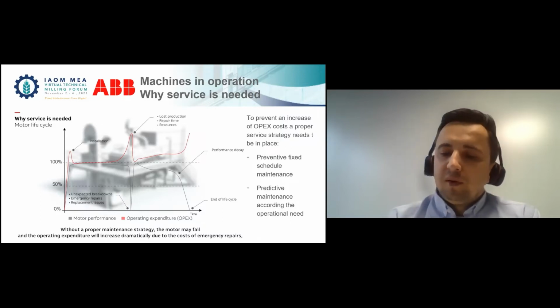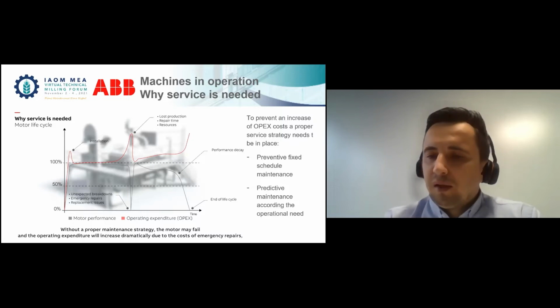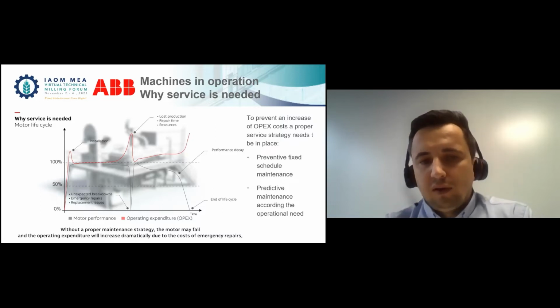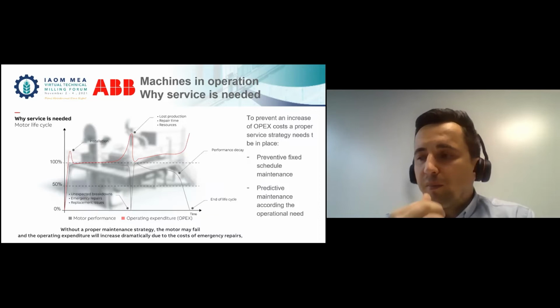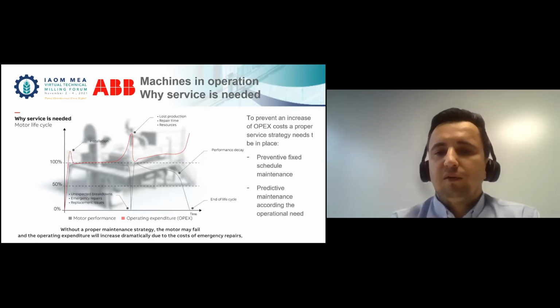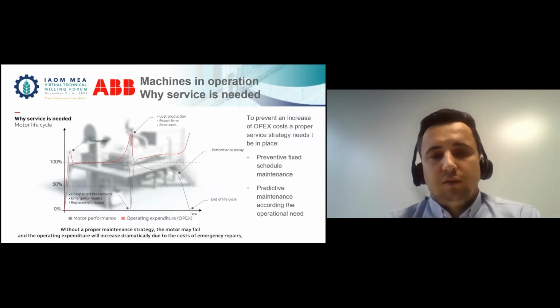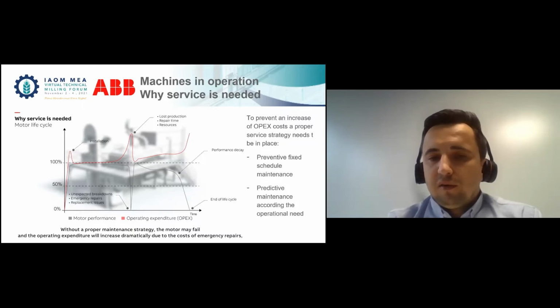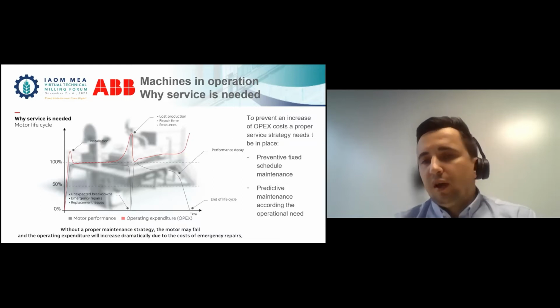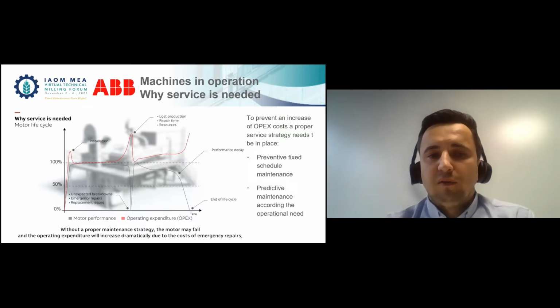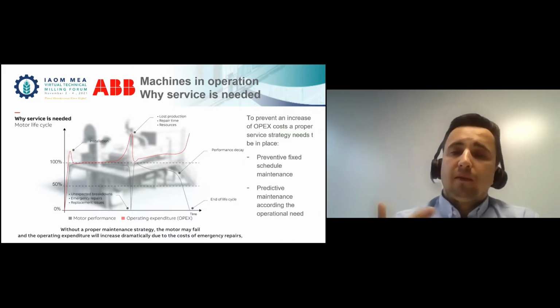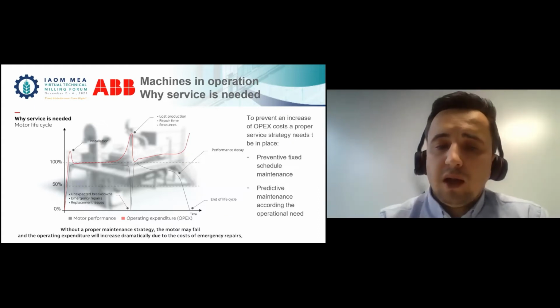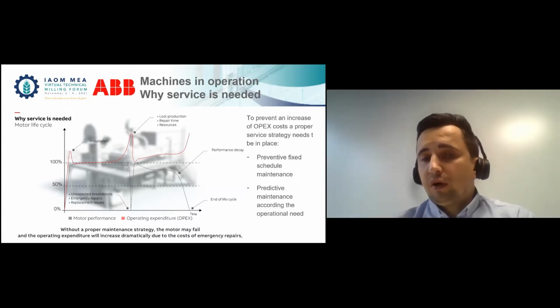But the motors do not come by standard with a specific grease, and this is also part of the application requirements, and very important. So if you have huge bearing forces, radial bearing loads and such, high temperature, high speed, you have to adapt your lubrication intervals to avoid unexpected breakdowns. This is the traditional way maintenance works for motors.